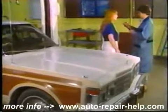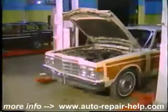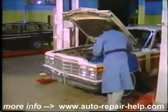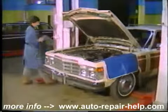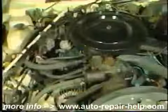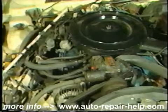Before working on an air conditioning system, make sure that you obtain an accurate description of the complaint from the customer. The next step is to perform a function test. That is, to check all phases of the system to determine if the complaint is legitimate. The service area should be well ventilated, and the ambient temperature should be at least 70 degrees Fahrenheit. To perform the function test, start the engine and let it idle for 5 to 10 minutes to allow the system to stabilize.